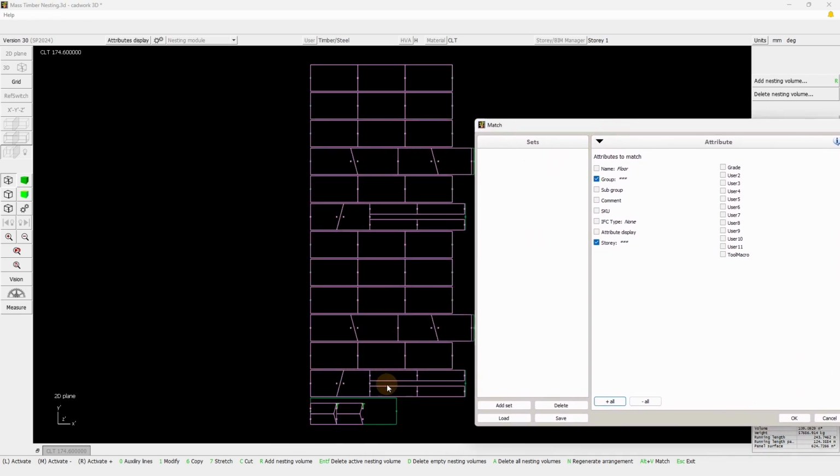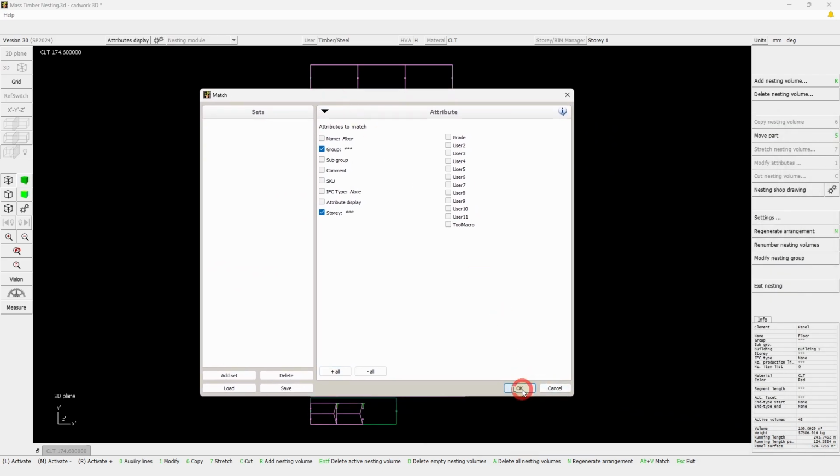The thing here that is really important, and this is what would happen at the bottom, is that since the elements within don't belong to the same group and the same story, this nesting volume won't be able to take any of those attributes. A nesting element can only inherit attributes if they are identical throughout their content. The following attributes of nesting are different, story and group, okay?